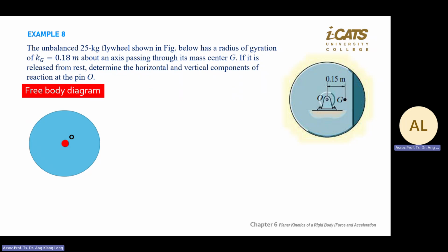The M is 0 because you are free to rotate, so there's no resistance of moment. Moment equals 0. Things that do not have resistance are always 0. For example, if you're free to move to the right, your force to the right is 0. If you're not able to move to the right, then there's a force resisting you.